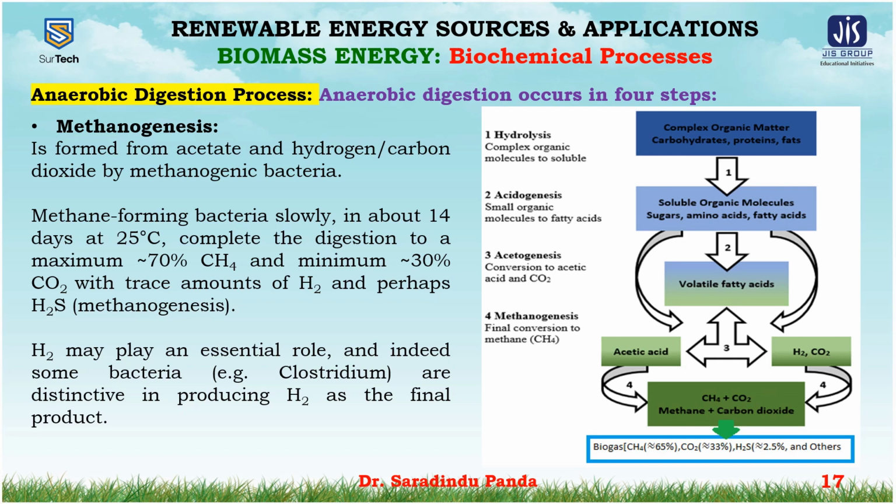The nitrogen should be present at 10% by mass of the dry input and the phosphorus at 2%. A golden rule for successful digester operation is to maintain constant conditions of temperature and suitable input material. Consequently, a suitable population of the bacteria becomes established to suit these conditions.